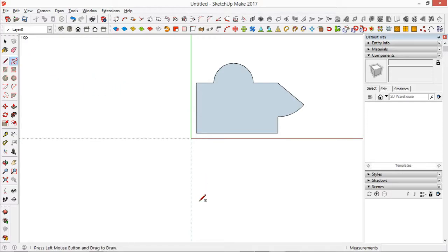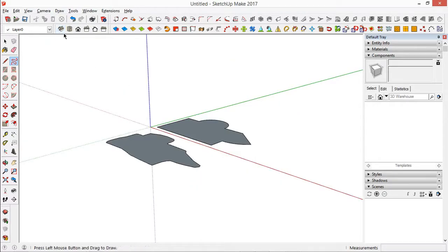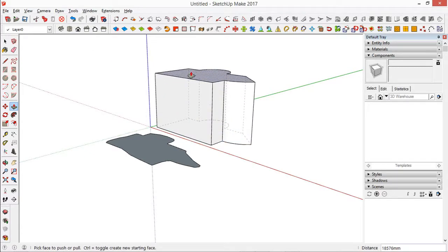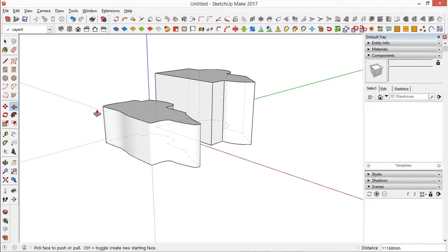Click Freehand command and draw the object similar to what you have just drawn. Start by holding the left mouse button while drawing and closing it at the same point where you started. You don't necessarily have to draw exactly as shown. What's important is you can follow the instruction on how to draw using the commands given to you. Now, turn them into 3D objects using the push-pull command.